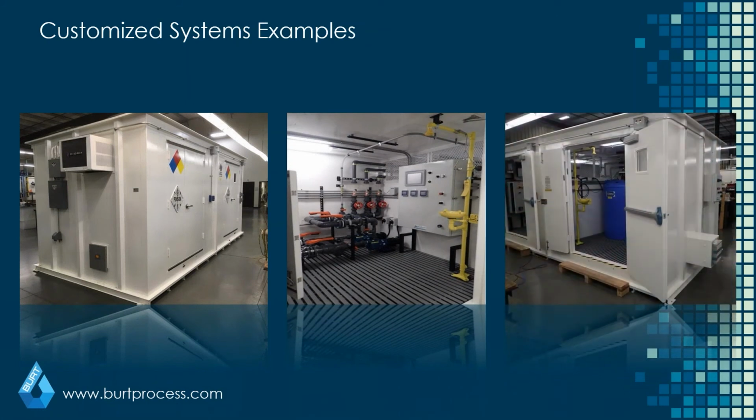When dealing with more hazardous chemicals, you can move into more of a modular building design, which is what you can see here. This is obviously more of a modular building design as opposed to a hot box or just a basic environmental enclosure. In these types of applications, you have segregation, for example. In this case, you have two different chemicals that, if they do combine, can be reactive. So they're 100% segregated between the two of them.